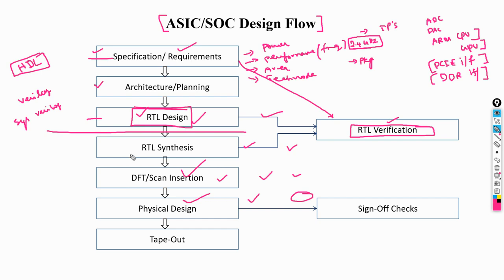So you would convert the code written by these guys into the form of gates. Say this is the gate level connections. Okay. Now, converting a simple HDL program into a gate level netlist, that is what we do in RTL synthesis.